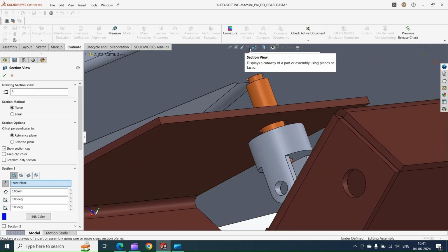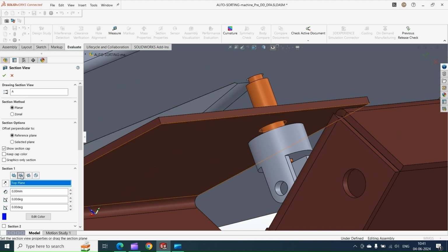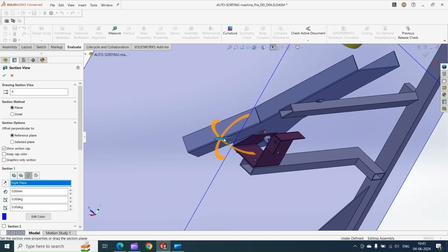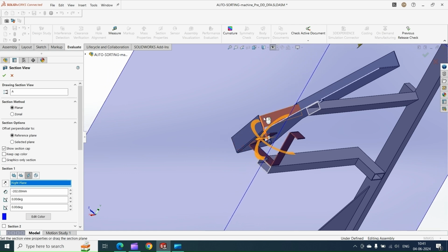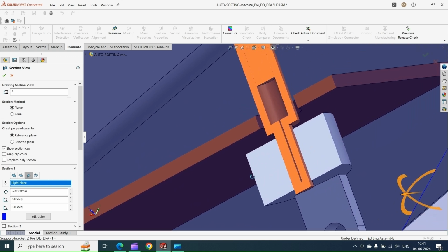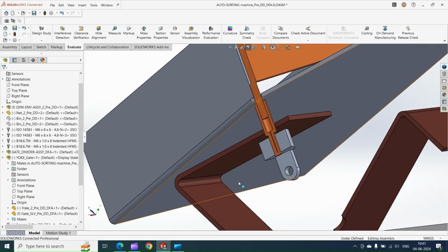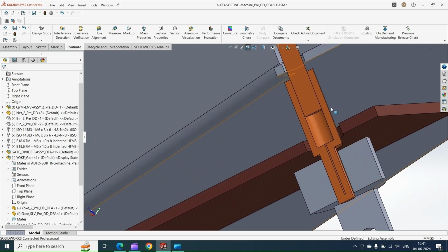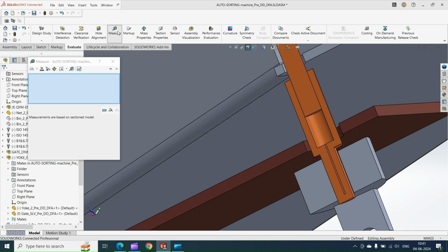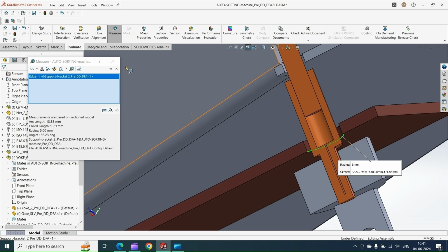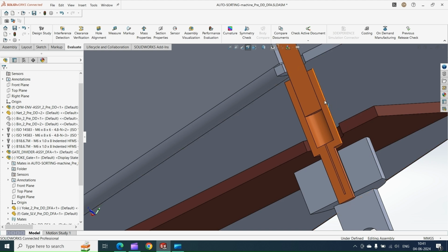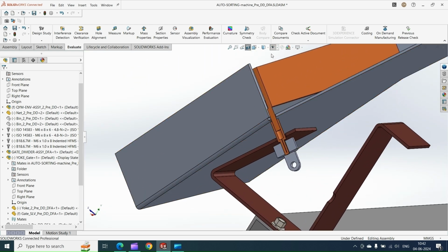Maybe I can take a section here to explain you better. So let me say okay to this sectional view. And what you can observe here is that the sleeve has fitted onto the stem by means of the interference fit, or you can add a set screw here to fix this. So both are acceptable, no doubt about that. Yeah. So you can see here the diameter is 10 mm and the diameter of this sleeve is 8 millimeters. So we get the radial clearance of 1 millimeter to fix this particular assembly onto the stem of the gate. Okay,